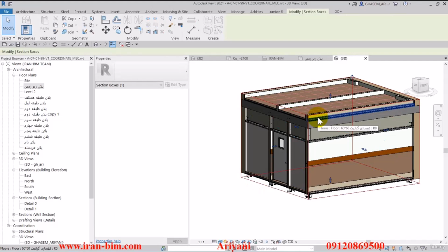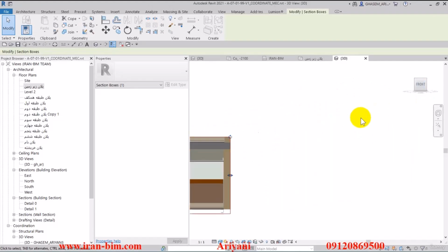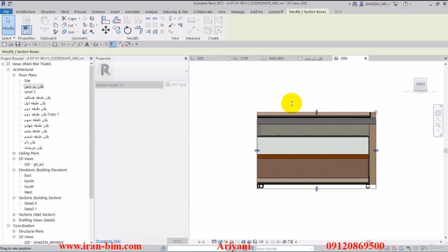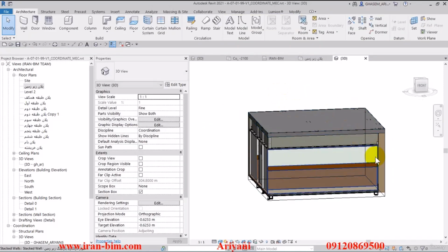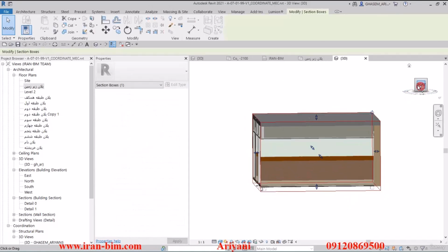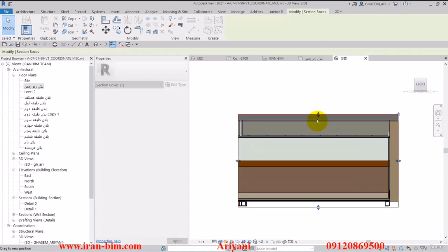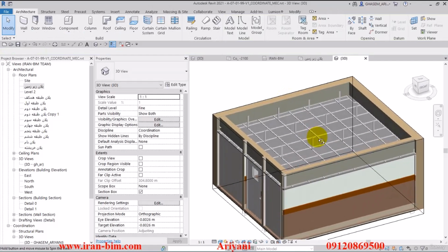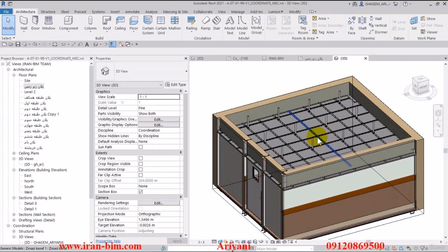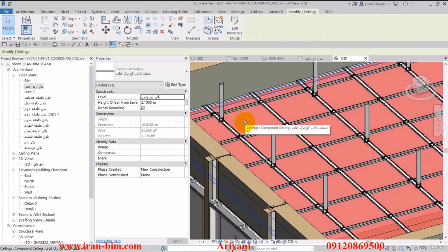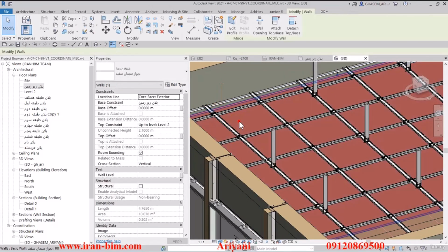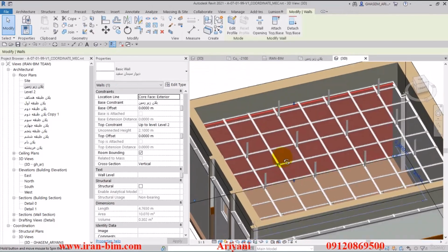When you're working with your own projects and you spot any motor houses or any similar structures, if you see in the plans of the AutoCAD file some suspended ceiling structures reserved for these spaces, first you need to question the designer whether this is actually true and we need suspended ceilings in these areas, and 99% of the time it is not actually needed and you'll need to delete the suspended ceiling.